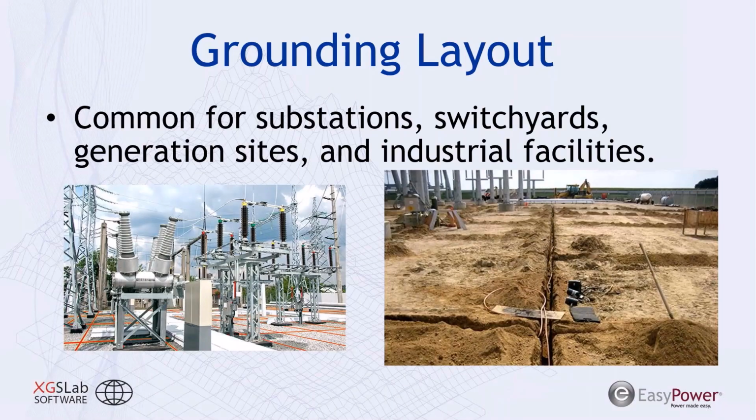For those of you that are not familiar, grounding systems are common for substations, switchyards, generation sites, and some industrial facilities. And these are essentially buried conductor into the earth. And you can see on the right, we have a trench that they're placing bare copper into the earth. And then they're just going to backfill that. And that's going to be the basis of our grounding system.